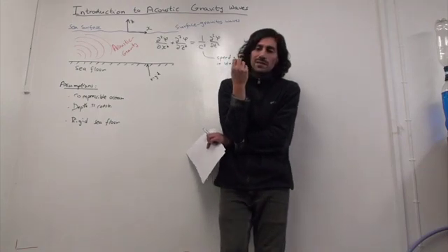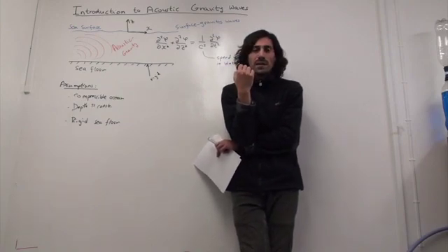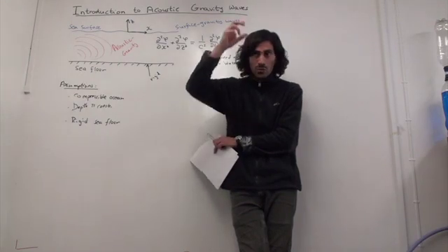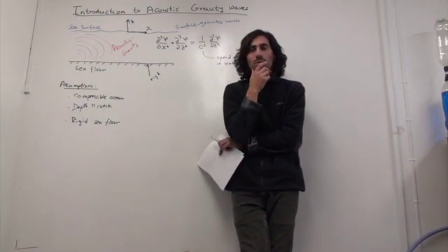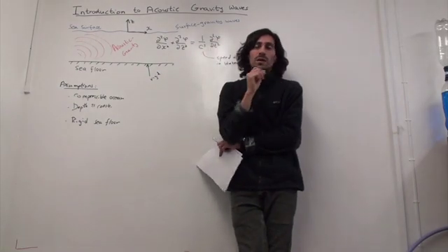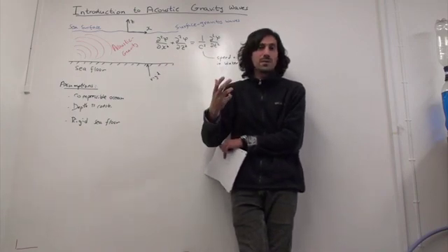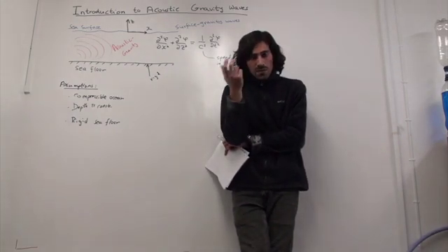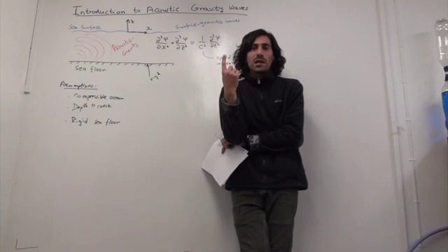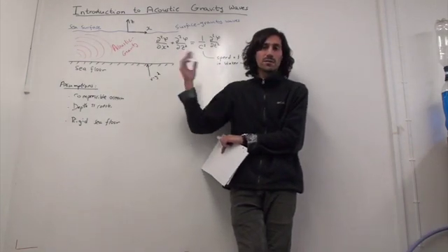Now again, the challenge is to translate the physics into mathematics. What does rigid mean? Rigid means that you cannot penetrate through it. So if you think in terms of velocities or position, as we had the masses and we always looked at the positions and how they were moving, things can go up and down, right? And they might go also right and left. But when it comes to the bottom here, they won't be able to go down. This is the meaning of rigid. You cannot penetrate through them. So to translate that into mathematics, I would say that the velocity in the z direction, w if you want, is 0 there. Okay, for any x, anytime, the velocity there is always 0.